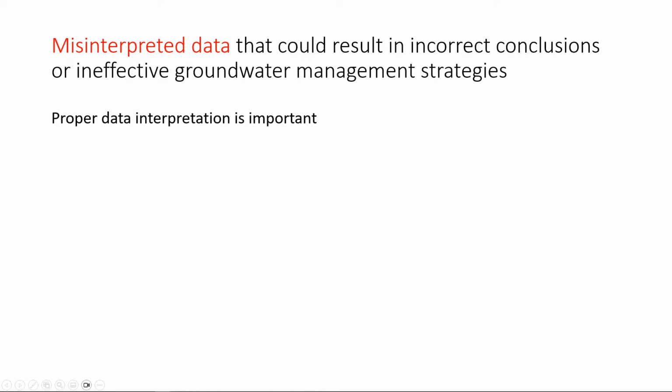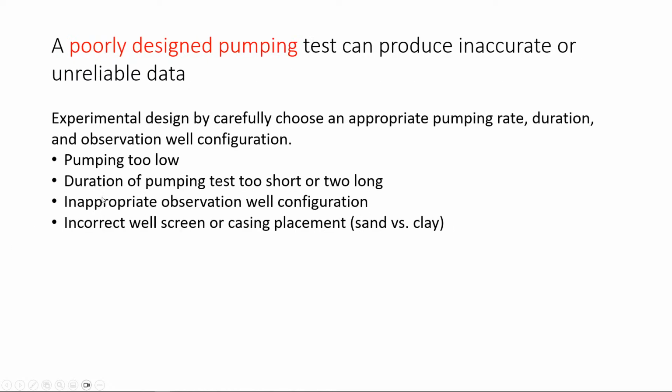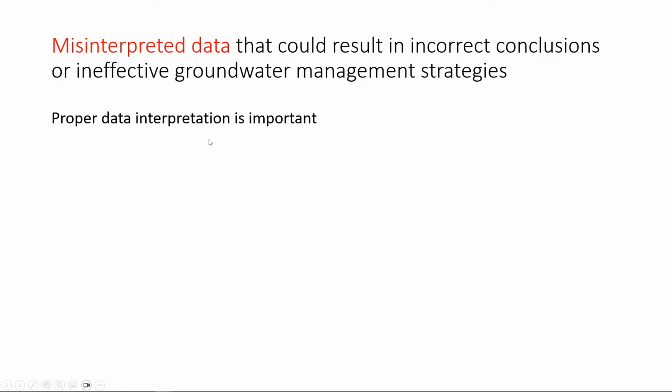Now, you can poorly design the pumping test, which would produce inaccurate or unreliable data, and then you have to repeat it. But you can also conduct an accurate pumping test and then misinterpret the data, and that will result in incorrect conclusions or ineffective groundwater management strategy.